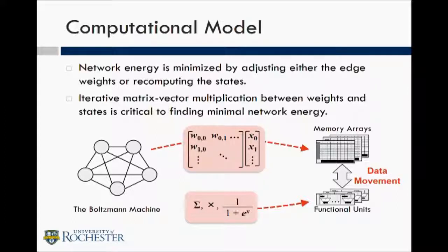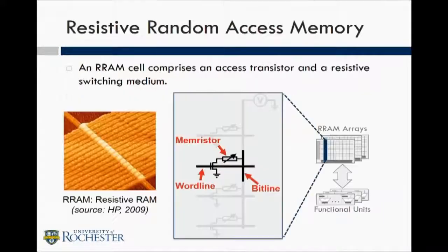We wanted to, rather than design yet another functional unit or customized execution engine, actually do computation in situ within the memory cells themselves. In other words, we wanted to compute in the analog domain, and when we access one of these arrays, what we want to read out is not one of the operands. We want to actually read out the result of the matrix vector multiplication directly in the analog domain from the memristive arrays. Here is how we propose to do this.